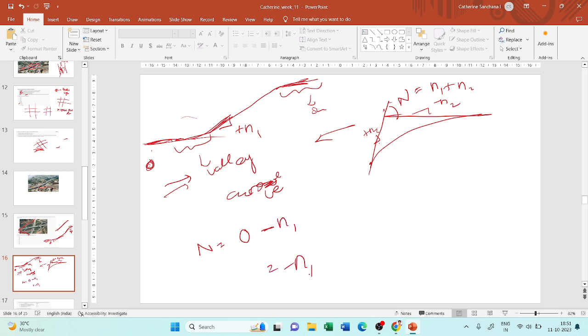That is why it is a valley curve. Now let us say we travel here. We have come to this point now. Here it has a positive grade of say plus n2, and again it is going and reaching a constant straight road which has a slope of 0. So what will be the deflection angle for these two gradients? It will be n2 minus 0.